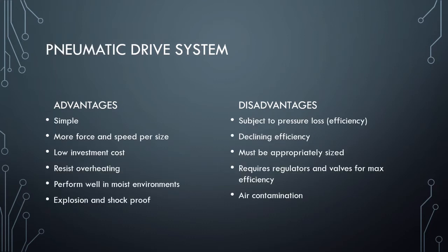Next, we have some of the more detailed advantages and disadvantages of our pneumatic or air-powered drive systems. One of the advantages is that they're simple. Pneumatic systems are air-based, which makes them a much simpler system. There are not a lot of electronic components like with the electrical drive systems, and we're not dealing with a hydraulic fluid like in a hydraulic system. Compared to our electronic drive systems, pneumatic ones have a lot more force and speed per size, so these could be a little bit more powerful.